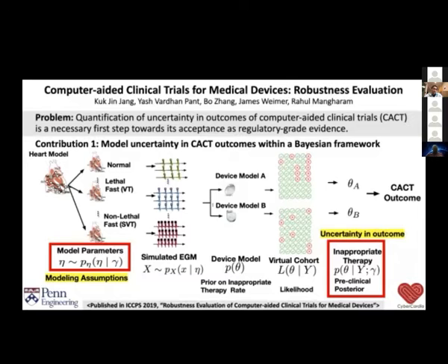So then we said, okay, well, how can we use our heart model, but now not just a single heart model, we generate tens of thousands of these heart models and variations of them, and feed these signals of these devices to them to understand what is the robustness of these algorithms? When do they fail? When do they actually cause the patient to go into unsafe conditions? But looking across large populations where you have intra and inter-patient variability.